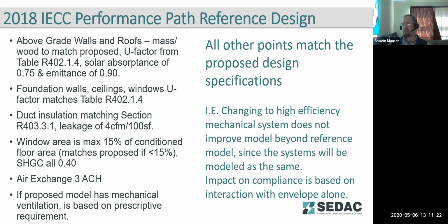And I do know in the next code cycle, Illinois is planning to align with the rest of the IECC jurisdictions and align with that 3 air changes per hour. As far as renovations go, air changes per hour is not a requirement to check in those buildings unless you're doing a full house renovation where you're essentially ripping the walls down to the studs and starting over from scratch.